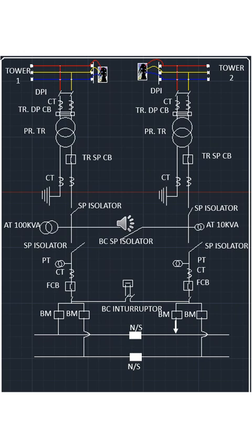Then generally in the conventional system we are using a single phase transformer. But this single phase transformer is using two phases. Here in the picture I have shown red and yellow phase. Why two phases? Because the phase to phase voltage is more. If I use phase to neutral, then the voltage will be reduced. So we are using two phases in the single phase transformer. Here it is red and yellow.